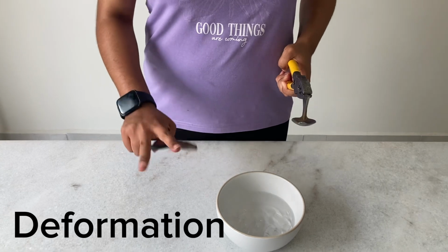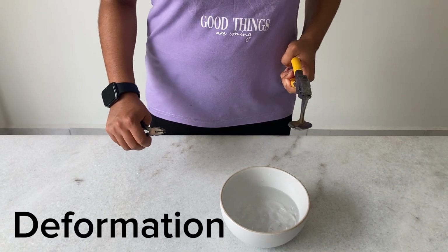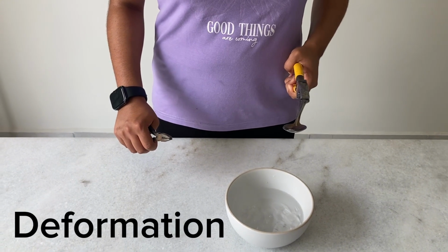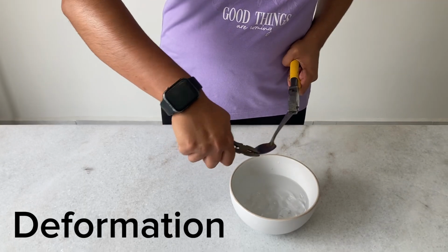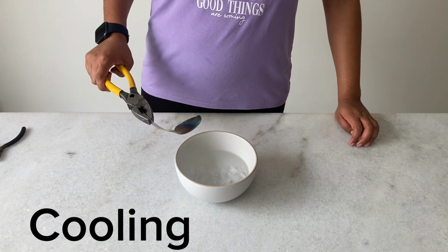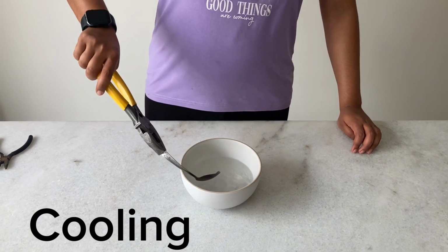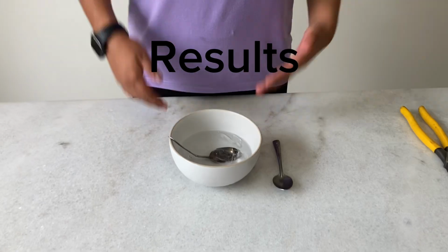Deformation. Second step, we apply pressure on the tip of the spoon to bend it. Here we notice that it is easier to bend when it is hot. Cooling. Third step, we submerge it briefly in cold water and we will see the resulting hardness.